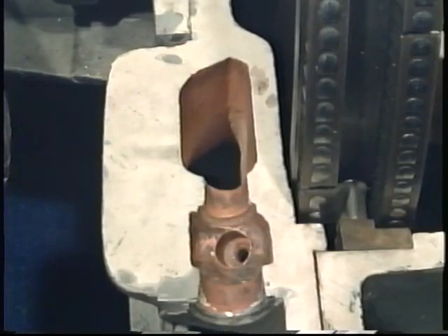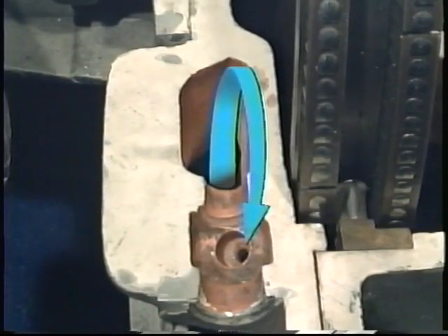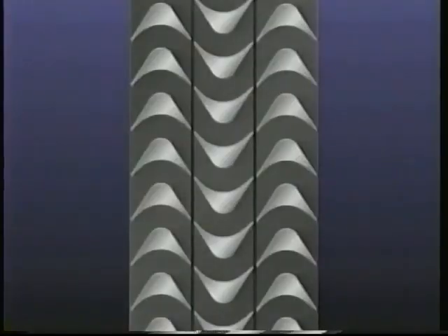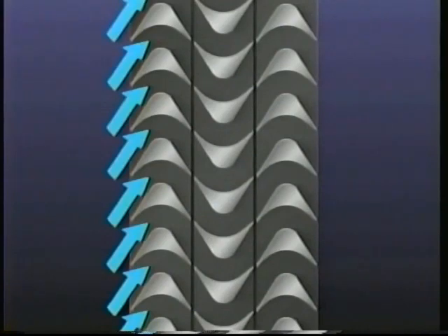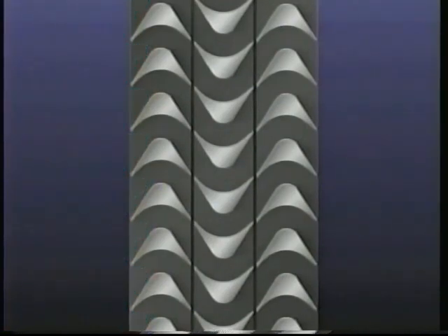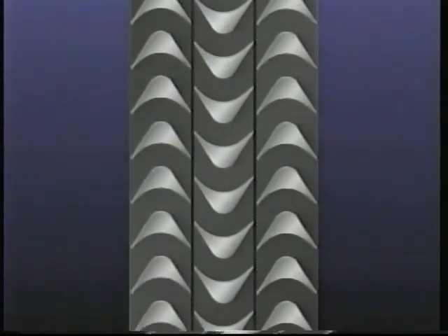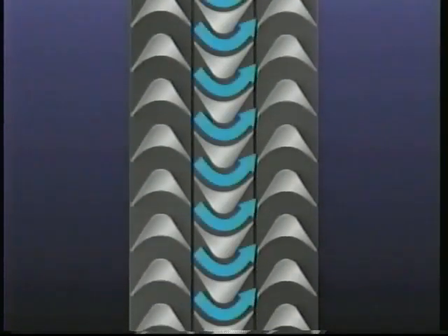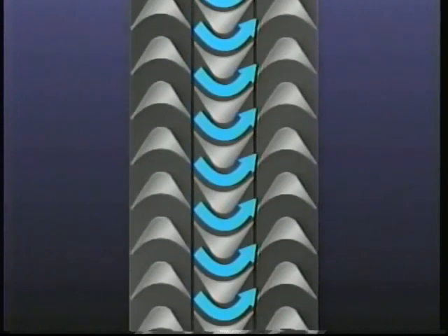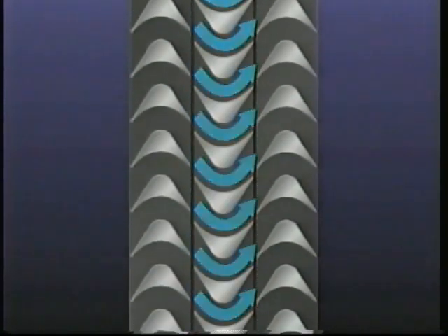As we discussed earlier, nozzles are the components that increase the velocity of the steam. The high-velocity steam from the nozzles is directed onto the first set of moving blades. This causes the blades and the shaft they're mounted on to turn. Then the steam flows through the fixed blades. These blades redirect the steam flow onto the next set of moving blades.